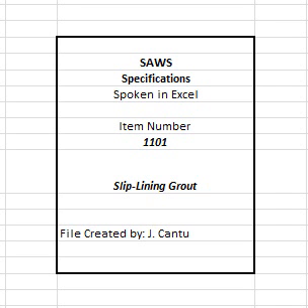A. Perform testing on the first pipeline segment to be grouted. Testing must be performed under observation by the inspector. If the grout does not totally fill the annular space, adjust the procedure or the mix, and rerun the test on the first pipeline segment. B. Density/viscosity. During placement of grout, measure density in accordance with ASTM C138/C138M-12A and C939-10, at least twice per hour. Adjust the mix as required to obtain the specified cast density.